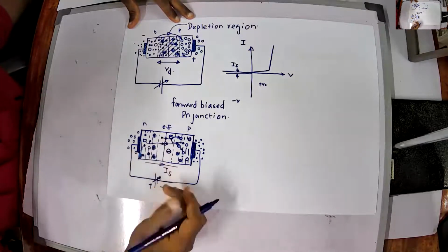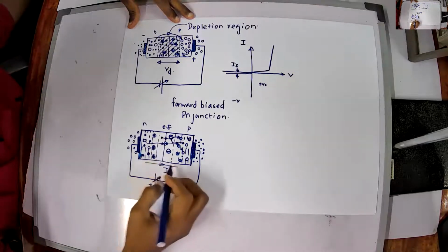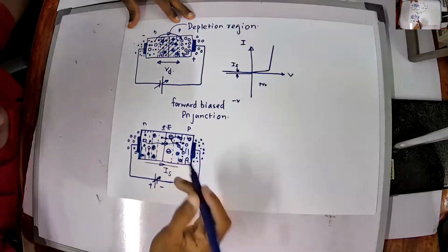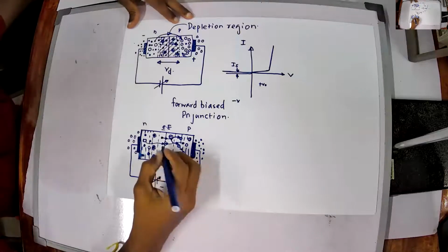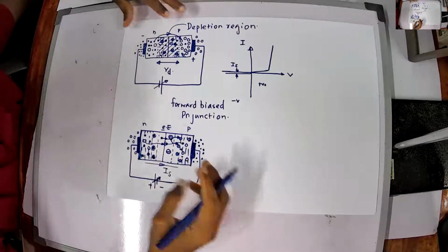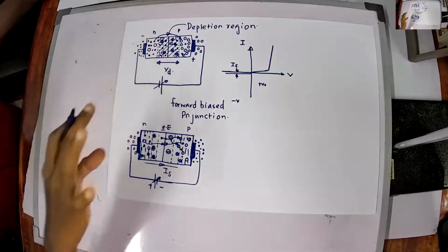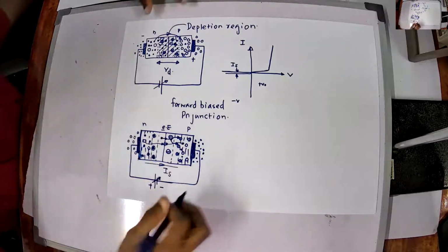This will be a rapid process once the voltage reaches a value which is sufficient to remove an electron from the bond. We could say that the diode has actually broken down, which means the electrons can be pulled off from the bond, accelerated towards the other bond, and they can hit another one, and then they can multiply.